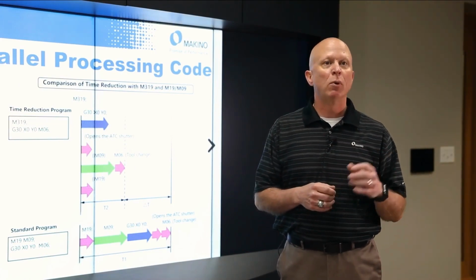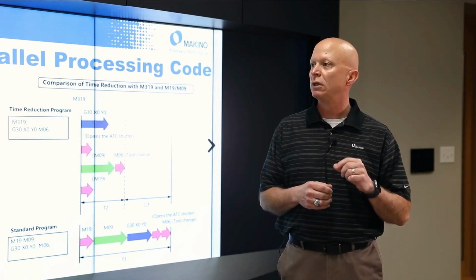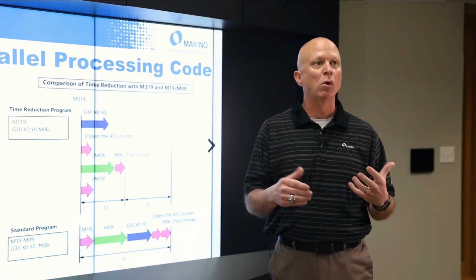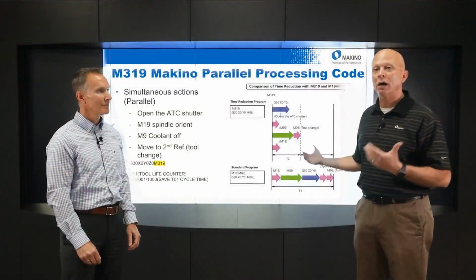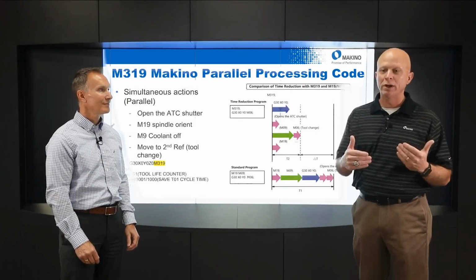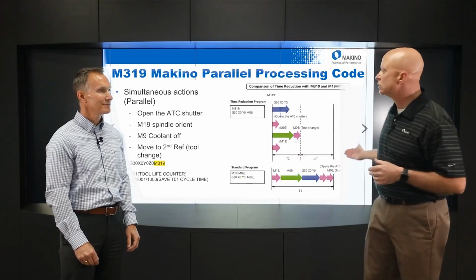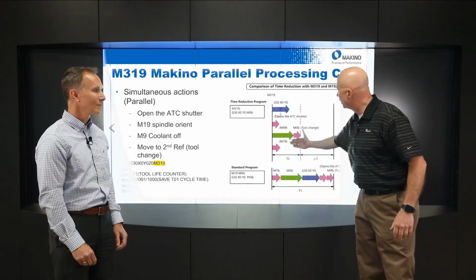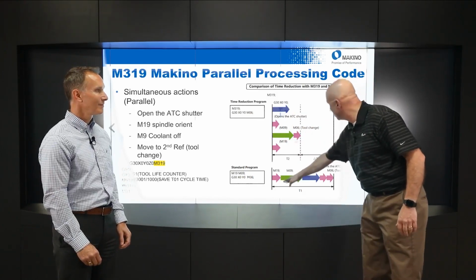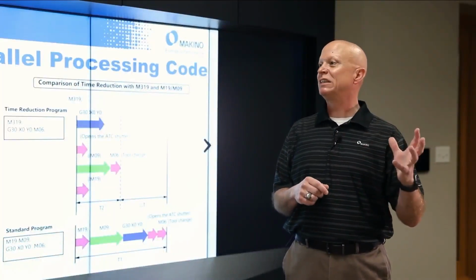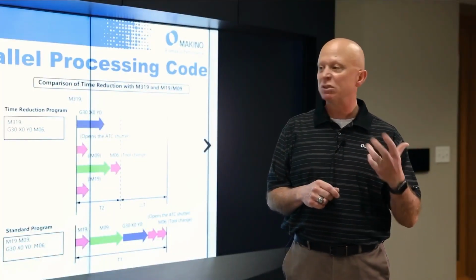It could save you upwards to 2 or 3 seconds per tool change compared to the alternative, which is kind of a historically traditional way of programming, and that is shown graphically at the bottom, and that is all those tasks programmed independently. Again, a very serial process, and graphically you can see your savings of all these different things happening all at the same time, as opposed to the serial process. And then your delta cycle time, again, could be 2 or 3 seconds per tool. Now, if you think about that, over a 30 or 60 tool process, that is a huge, substantial savings.